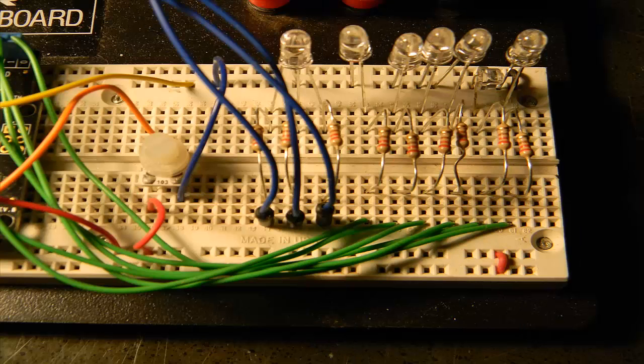This slide shows how the single color LEDs are wired up. They're wired up in order from left to right as red, orange, yellow, green, blue, and the far right one is an ultraviolet LED. I got all of the LEDs at Radio Shack except for the blue LED, which came out of a blue flashlight. You can see the green lines across the bottom, the green wires. Those are the wires that come from the digital output ports on the Netduino. You'll notice that I have resistors here between the Netduino outputs and the LEDs, again to protect the LEDs to keep them from burning up.